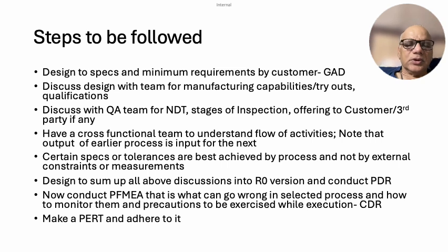Now with this we will be coming to a CDR. After PDR, after having done PFMEA, we will be doing the critical design review. It means now everything is frozen, qualifications are done, tryouts are done, achieving properties, tolerances or hardness, whatever the distortion levels after heat treatment or the fixtures, everything has been frozen, and we are now ready to launch our first article.